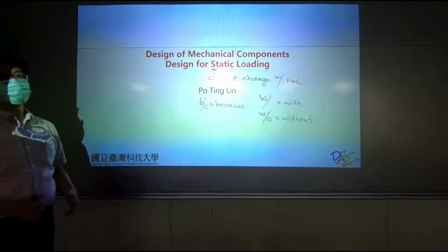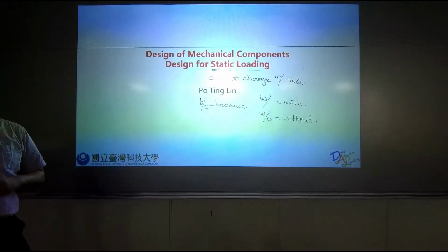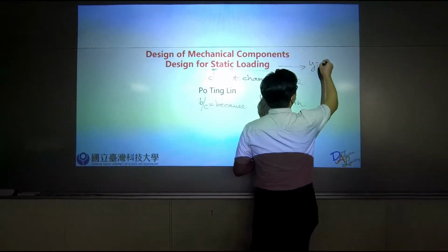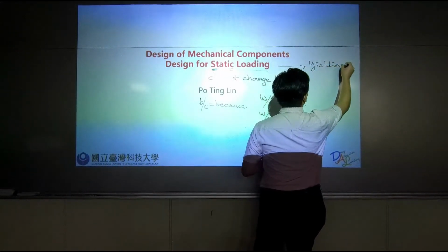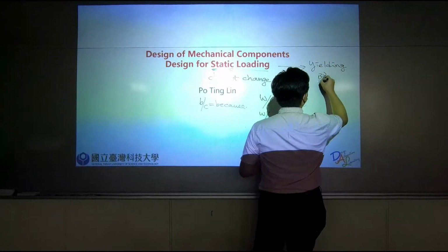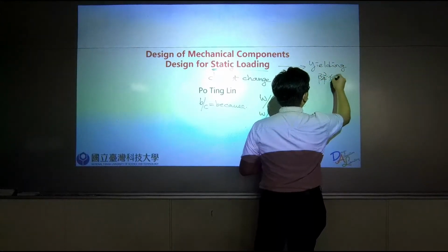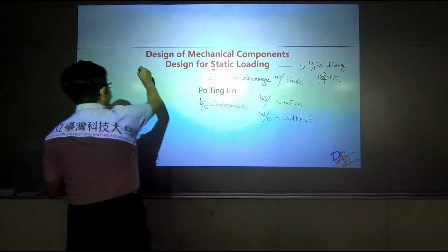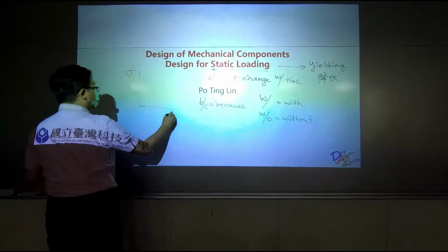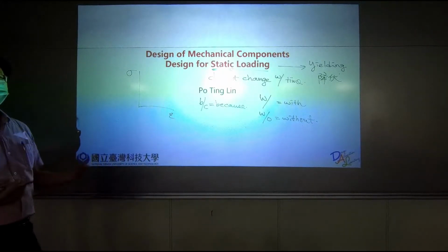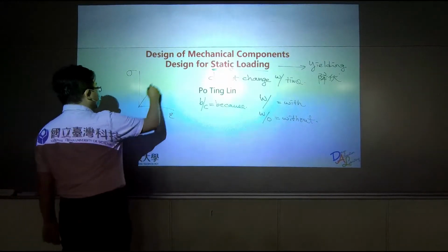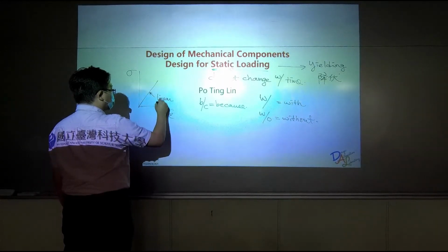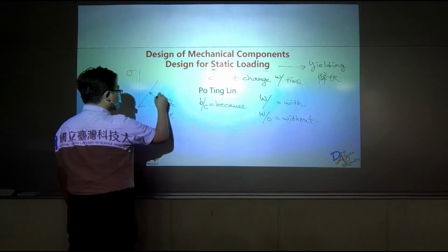In this kind of problem, what we are worried about is yielding. We worry about yielding because for materials, in the stress-strain relationship, we are mainly focusing on this linear region, the so-called elastic region.